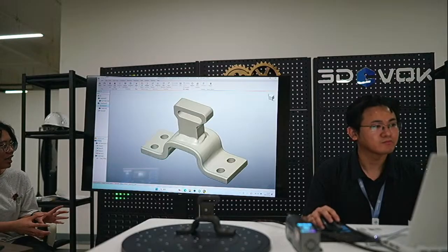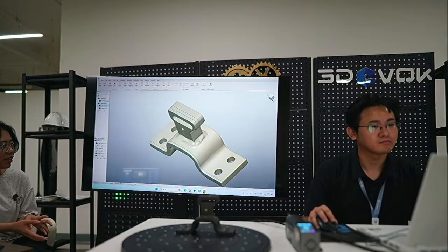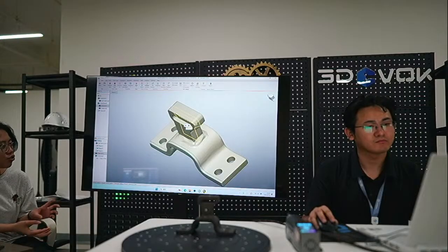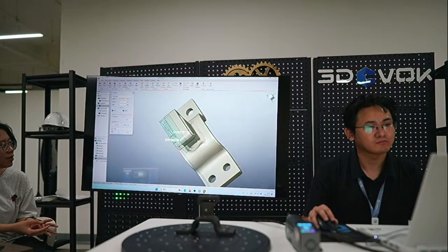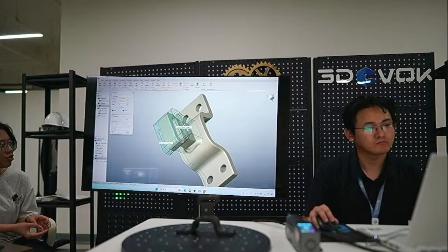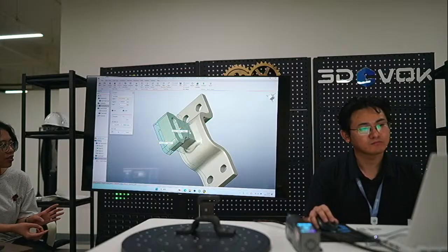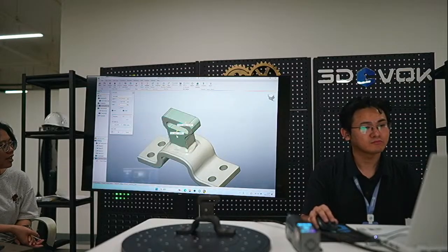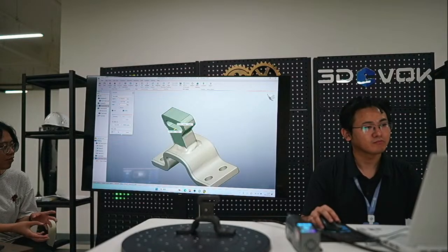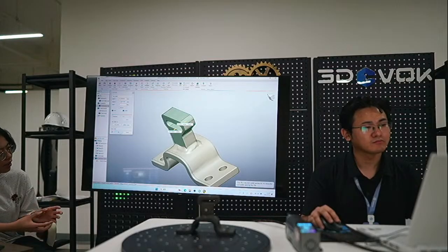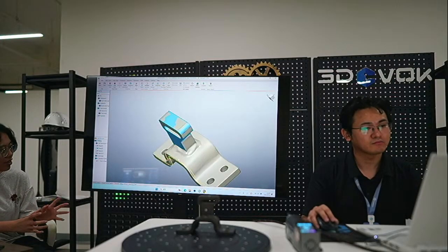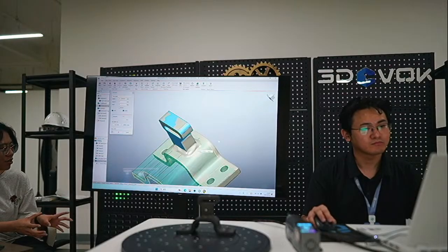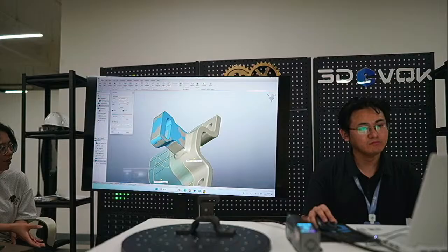So we have 2D sketches of the lower part and the upper part. The next step, we need to extrude both parts. We can drag the 2D sketch to fit the surface of the actual STL file, and we will do the same at this part. This can help us efficiently fit the actual faces of the STL files. We can get an accurate file.